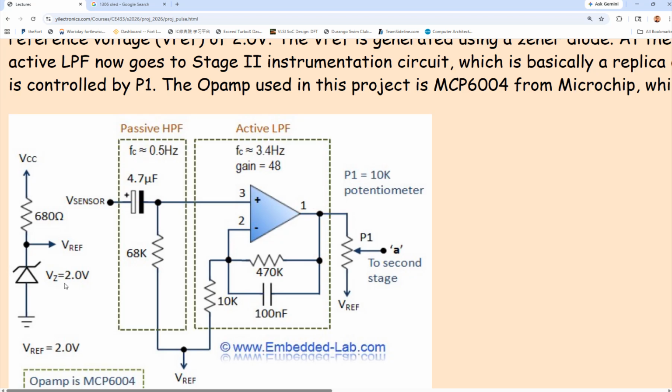Okay, and we reverse bias it. Just to break it down, whenever you have a resistor connected to VCC, it applies the voltage across it. Whenever it reaches 2 volts, it breaks down, and there will be a lot of current going through it. So whenever VCC increases, if we increase VCC, this voltage almost does not increase at all. How does that work?